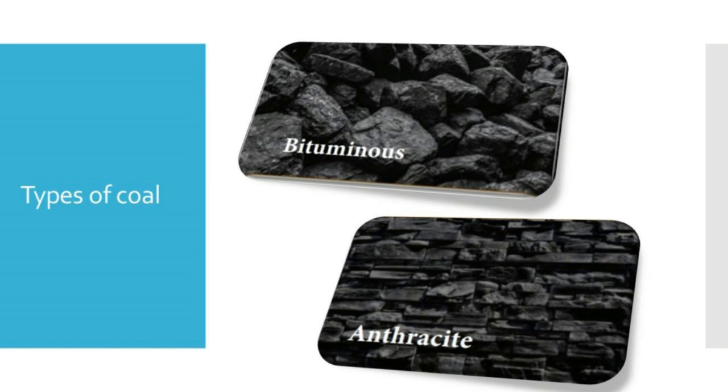Next, anthracite. Anthracite is the highest grade coal. It has a very light weight and the highest heat content. Anthracite coal is very hard, deep black and shiny. It contains 86 to 97 percentage of carbon and has a heating value slightly higher than bituminous coal. It burns longer with more heat and less dust.